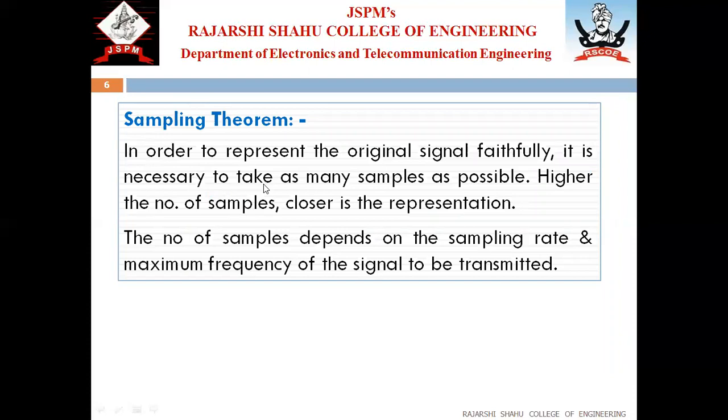Sampling theorem. In order to represent the original signal faithfully, it is necessary to take as many samples as possible. Higher the number of samples, closer is the representation. The number of samples depends on the sampling rate selected and the maximum frequency content of the signal which is to be transmitted or which we are trying to convert in discrete form.